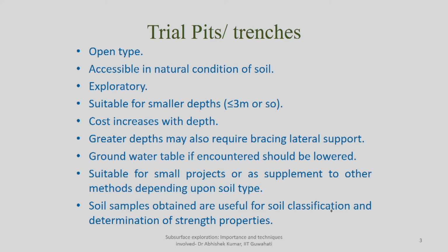So, you have a site for which you have given the chainage with reference to some nearby points, then you start digging, and you collect samples from different depths by means of a measuring tape. Every time you dig, you will also record, at this particular depth, this kind of soil, this kind of vegetation, these rubbles, gravels, cobbles and boulders, all things whatever you encounter at the site, you keep on making a log of that. As I mentioned, this is more suitable for smaller depth.